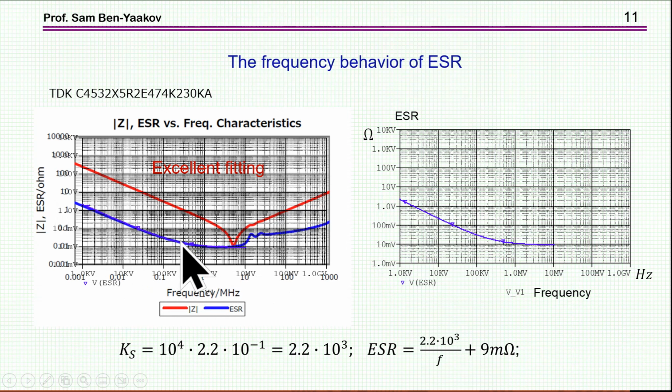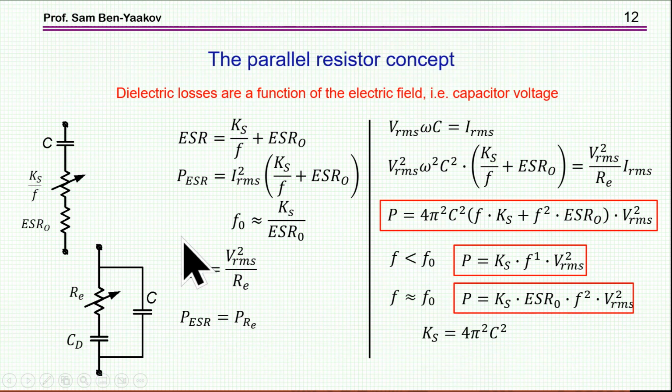So you can now take this relationship and work it out into the expression for the power loss. And lo and behold, we get something of this nature. This will be the expression for the power loss based on this model here. And as you can see, it fits very well with the Steinmetz prediction and with the ferromagnetic template that we are using in the case of ferrite material.